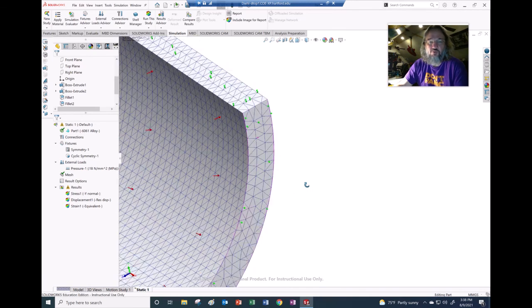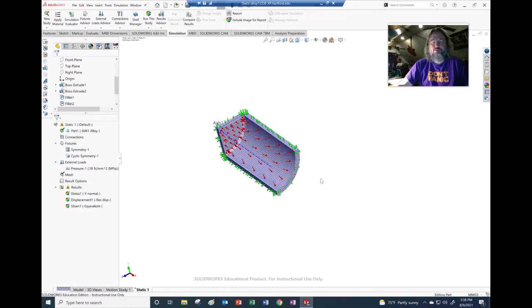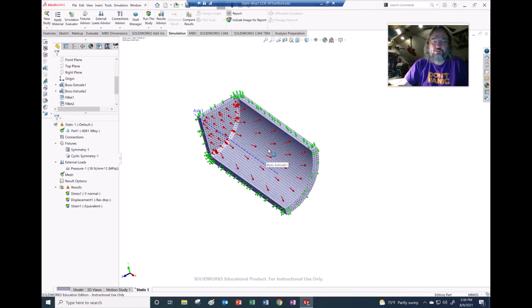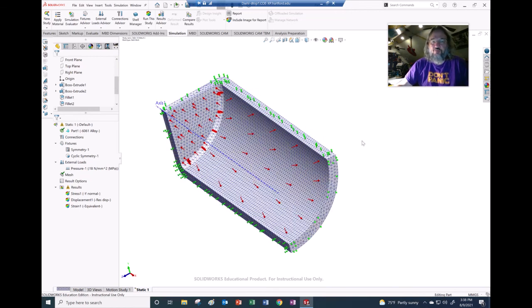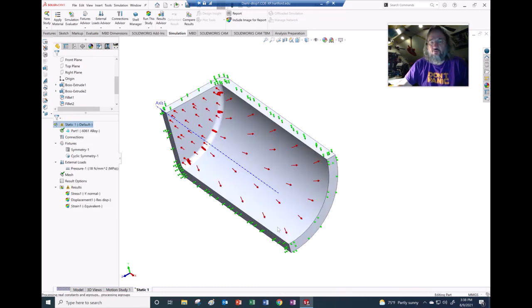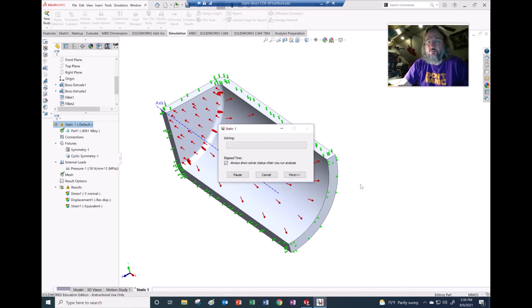That's going to improve the quality of our results. If you have something that's thin most of the time, you actually want to use plate elements. Plate elements are a much more advanced element to use in most FEA codes. This might take a little more time to run because there are a lot more degrees of freedom in the matrices that have to do the work. And it's going to make a liar out of me and just solve it really quickly.